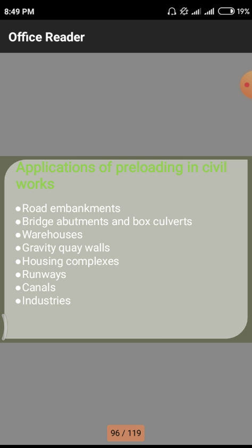But in the case of canals, plenty of water is traveling throughout the year, so if there is any entrainment of water into the previous structure, there is definitely a chance of breaking down parts of the structure. That means the sides of the canal will be eroded, and in some cases the sides of the canals will be swelling and shrinking. All these properties lie on those canals.